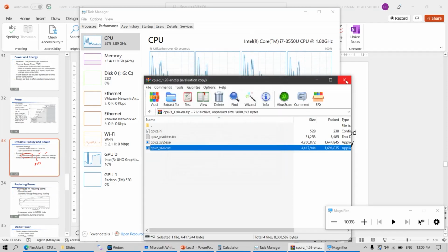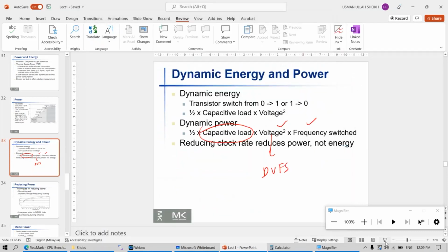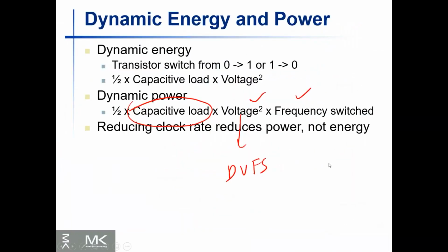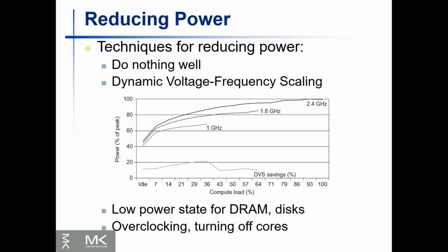You may think that, oh, you're just adjusting every millisecond, and that doesn't give a lot of improvement. Actually, that's not true. Every millisecond, if you can do very fine voltage and frequency stepping, that can actually save you a lot of power consumption over the total day. Okay, so that's voltage and frequency scaling. For other components of our computer, RAM can run in a low power state, drives can power down, and your LCD screen can dim and then turn off. And for your CPU cores, some of them can be turned off and some of them can be overclocked.